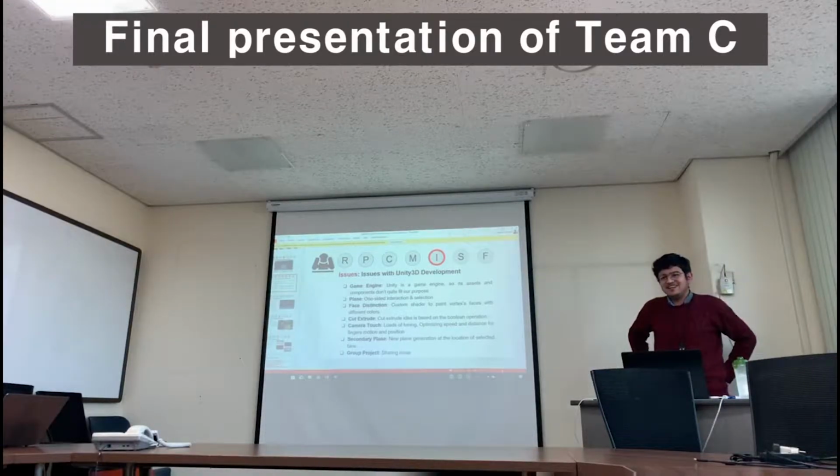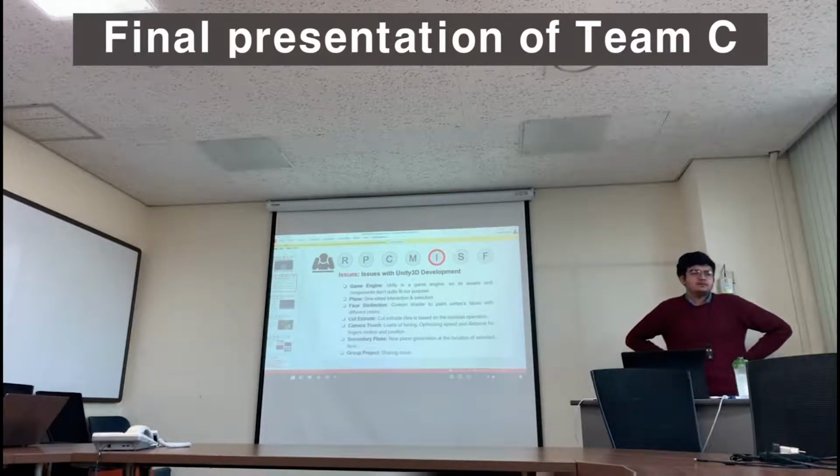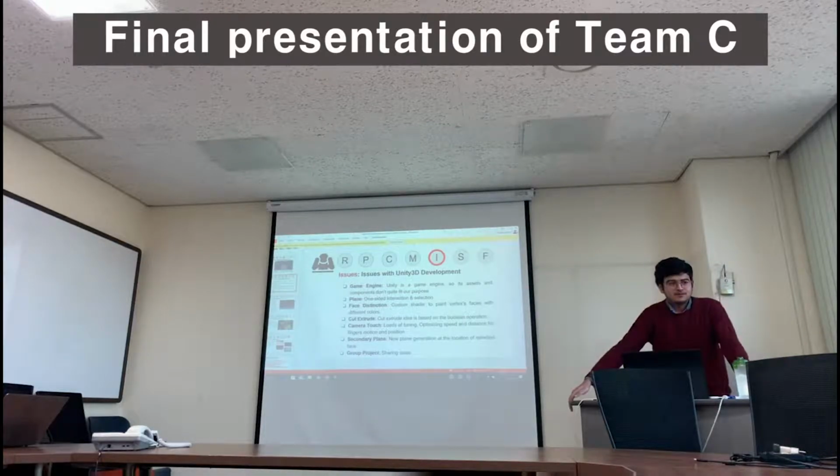You're not supposed to, but you can. Even with the polygon, the normal can be determined using the right-hand direction. The start point of the rectangle, circle or polygon is drawn from one point to the other, and that determines the direction of the lines. Then you can choose the normal direction. Thank you.